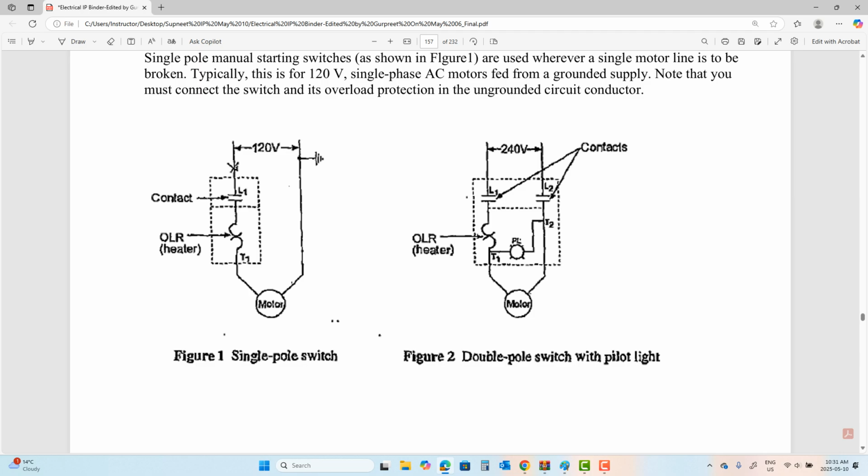Where are overcurrents? Overcurrents are not on the motor, they are on the supply side. So just be aware, in a motor we have both overloads as well as overcurrents. Overcurrents are on 28200, overloads are on 28306, depending on what was asked in the exam. What we are really focusing on is overloads, which is 28306 at the moment. So stay with me on the screen.